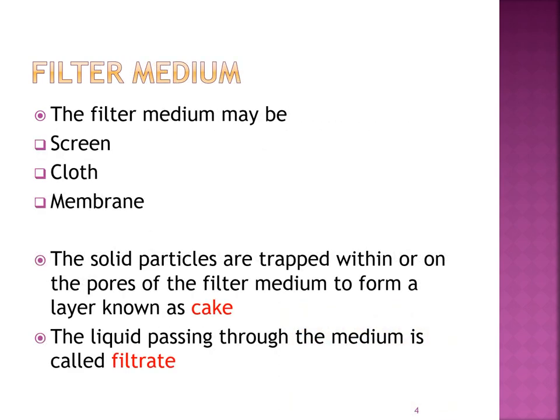The day-to-day application of filtration includes water purification, brewing of coffee, air filtration, and also separation of the lemon seeds from lemon juice. The filter medium, as I said, can be made up of a screen, cloth, or a membrane. The solid particles which are trapped within or on the pores of the filter medium is known as cake. The liquid which passes through the medium is known as filtrate.